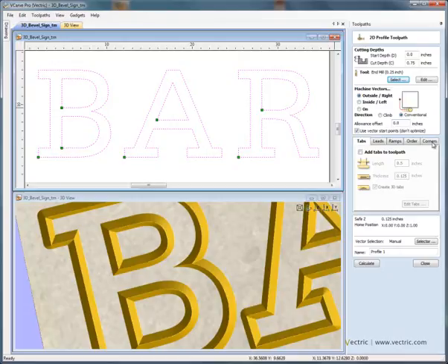And we want the cutter, again, to use sharp external corners. But the very important thing here is if we cut using the 1/4 inch cutter onto the edge of the text or the font, then we're going to machine away the chamfer. So what we need to do is offset the toolpath outwards by the allowance that we looked at for the previous chamfering toolpath. For this cutter, the offset allowance needed to be 0.4 of an inch. So that's going to offset the toolpath outwards and it will machine to the base of the chamfer, giving us the result that we want.